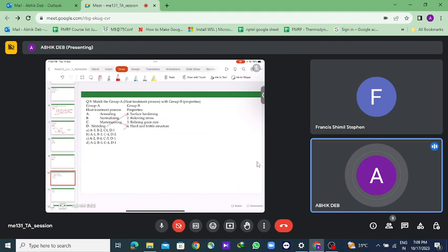Okay, sir. So, do you know how martensite is formed? It is a diffusionless transformation in which a BCC structure, that is body centered structure of carbon and iron, gets transformed to body centered tetragonal structure.